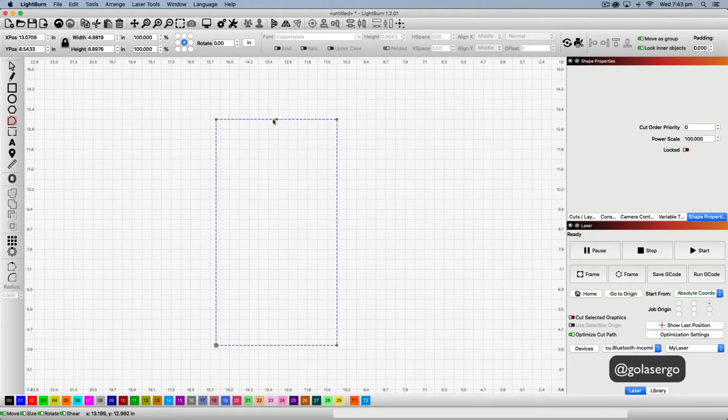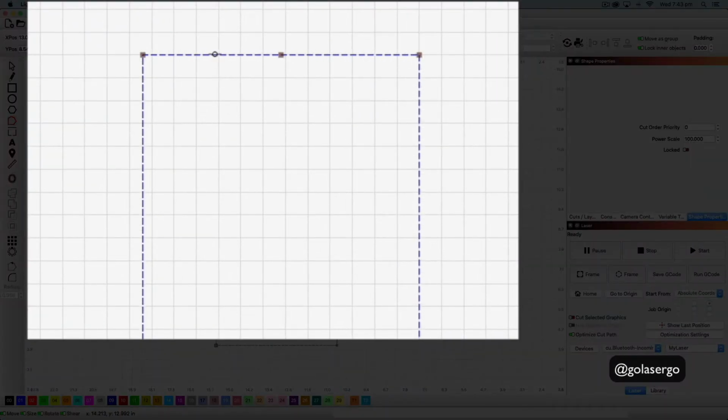So in order to do that, we just run our mouse around this middle here between the 2. Remember, it's trying to find the middle always between 2 nodes. So you're going to get a circle appear here now between these 2 nodes. So it's showing the circle. So I press I on my keyboard. And same on this side, I'm just going to press I. Okay, so I've got 3 nodes there now.